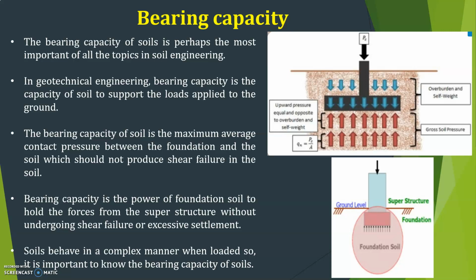Such a ledge or rock or other stiff material may not be available at reasonable depth, and it becomes invariably necessary to allow the structure to bear directly on the soil, which will furnish a satisfactory foundation if the bearing members are properly designed. It is therefore that the subject of bearing capacity assumes significance.